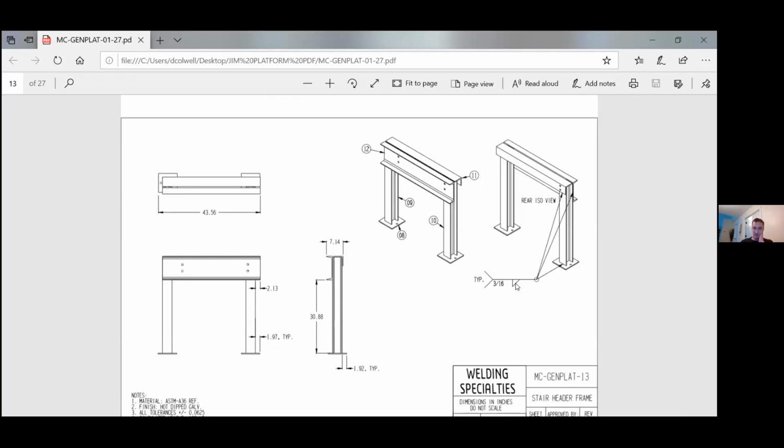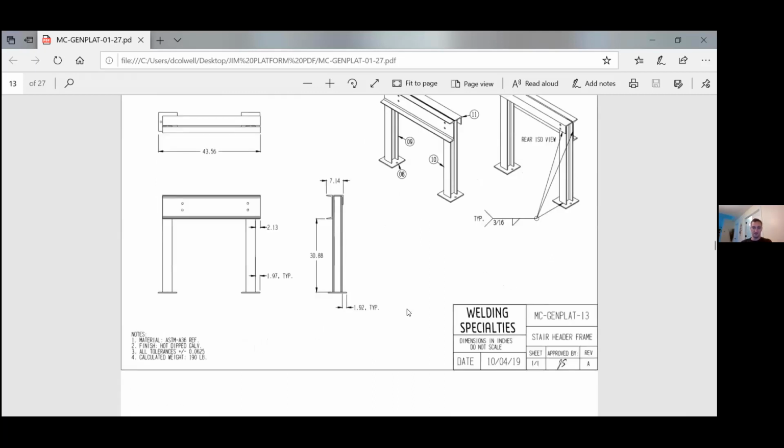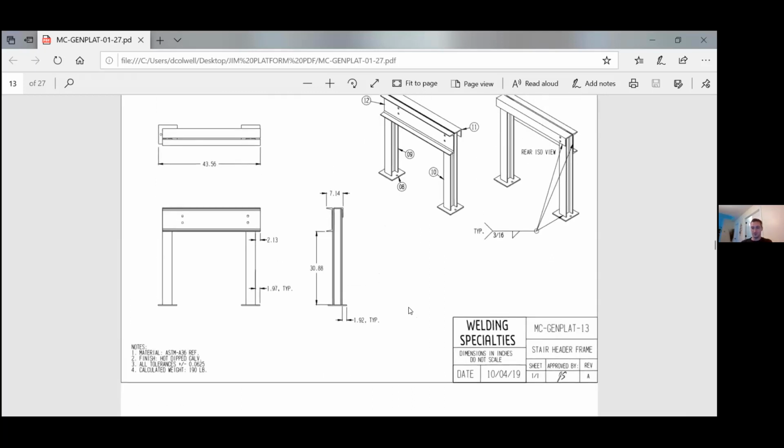If you guys are planning on doing any welding at assembly, after this thing's put together, then you end up putting a little flag out here and it becomes a field weld. And that just means it's not welded during the manufacturing process. It's welded sort of at the site, at the final resting place of this thing. That's probably not what you guys are going to do though, but if you did, then there's a field weld symbol to put on there. But there are lots of different options with weld symbols. You should probably just research them.